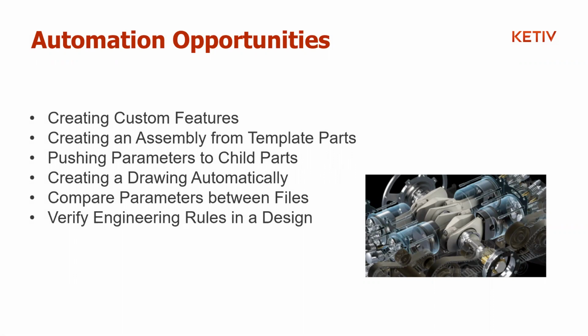Some of the things we do as a team: you can create custom features that you can add onto existing parts if you're doing the same thing over and over again. You can also create an assembly from a library of template parts. We do this a lot, and it can provide customization and automation that will allow you to get a design out quicker and with less engineering hours.